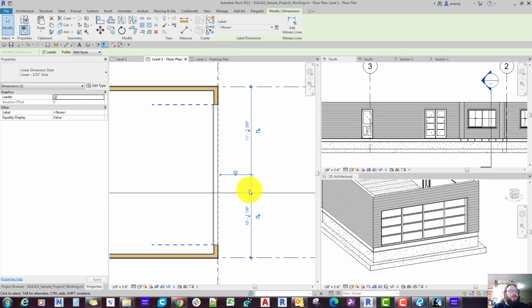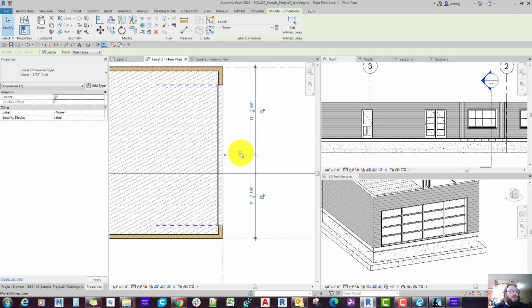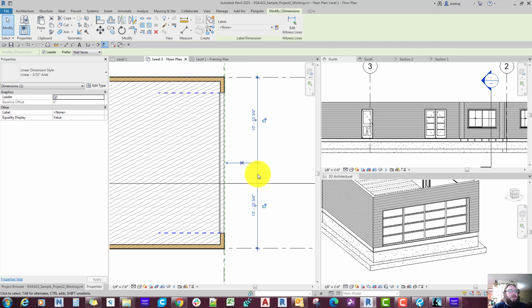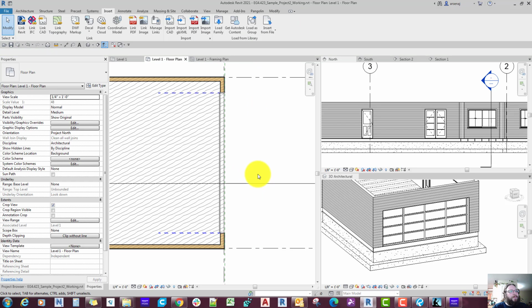Another thing, when you have dimensions that are placed, if you want to make an element equal, there's a little equal that's crossed out here. You can click equal and it'll equal it up inside that space between those 2 dimensions. So we're good.